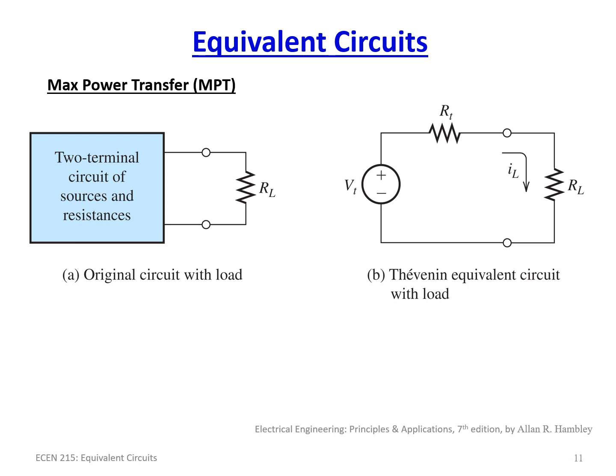So another useful thing about Thevenin equivalent is that there is a point in which the maximum power is transferred. And this is simply due to the fact that we have a resistance now that's in series, and we're going to attach some load, some device to this circuit, and we're going to drive that. So this load is what is being connected to the terminals of the Thevenin equivalent.